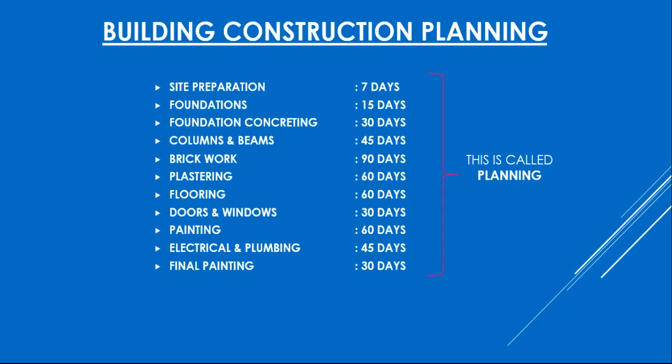Like that, you have to differentiate between the task and subtask. If you add the durations for all the subtasks, the duration for the main task, for the foundations, will come automatically. This is how you have to do the initial part in Microsoft Project, and that we are going to do here. Till the critical path method, we are going to calculate and execute this project.